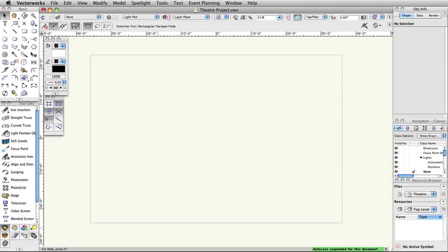There are 2D locus and 3D locus tools located in the basic palette and 3D modeling toolset respectively. Locus points and datums provide guides for drawing and reference points as needed. You can also convert locus points and other objects into guides. This will move the objects into a guides class, modify the attributes of the objects, and lock them in place.